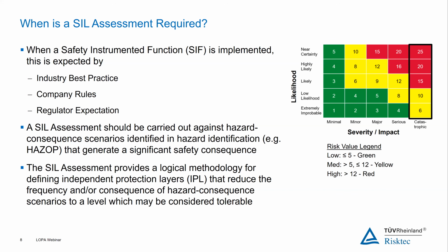And while I refer to these two methods as complex LOPA and simple LOPA, while they are often defined separately, sometimes you'll find that what is mostly a simple LOPA may incorporate one or two elements from a more complex LOPA. So it's not a hard and fast rule for the most part that defines both of those, although often it is stated when you're setting out to carry out a LOPA which one you're going to aim for and which one you're going to try and do.